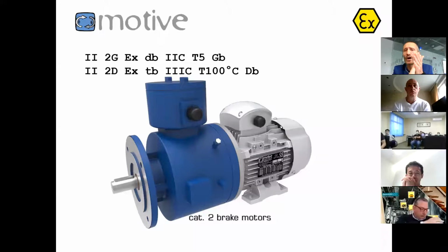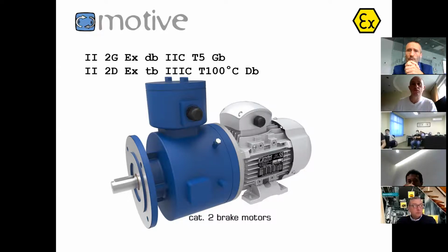We can't know how intensive the brake use is going to be. Therefore, it could generate too much heating internally. The only way was Ex d. So here we mix an Ex e product, the motor, with an Ex d brake. Why not? They are both suitable for the same risk category.